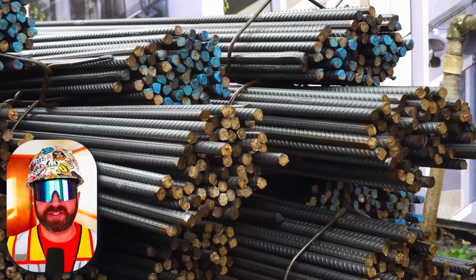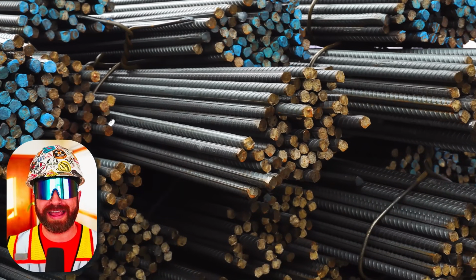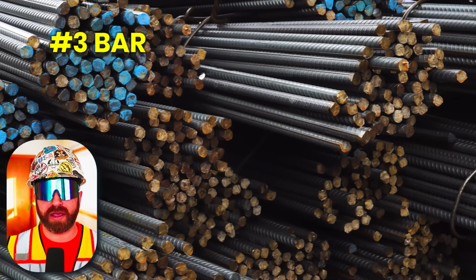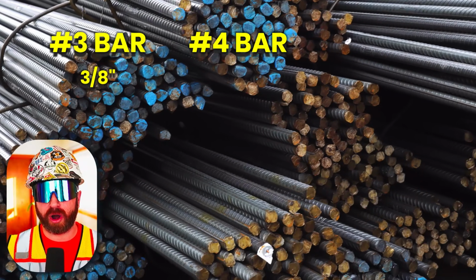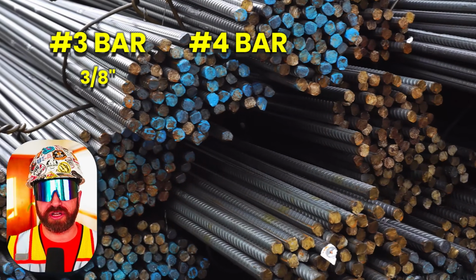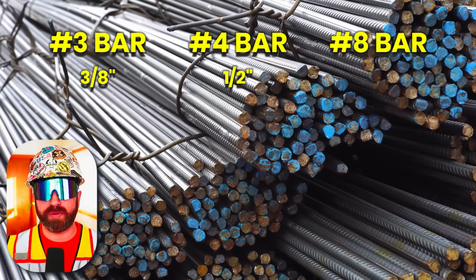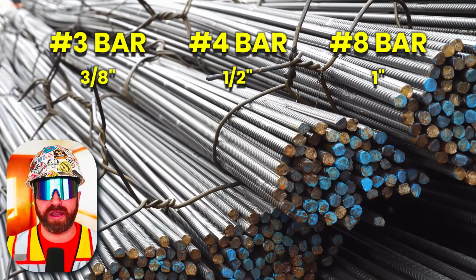Rebar also comes in different sizes, which is the corresponding diameter of the bar in eighths of an inch. So a number 3 bar is 3/8 of an inch in diameter. And a number 4 bar is 4/8 of an inch in diameter, or ½ inch when simplified. Number 8 rebar is 8/8 of an inch, which is the equivalent of 1 inch.